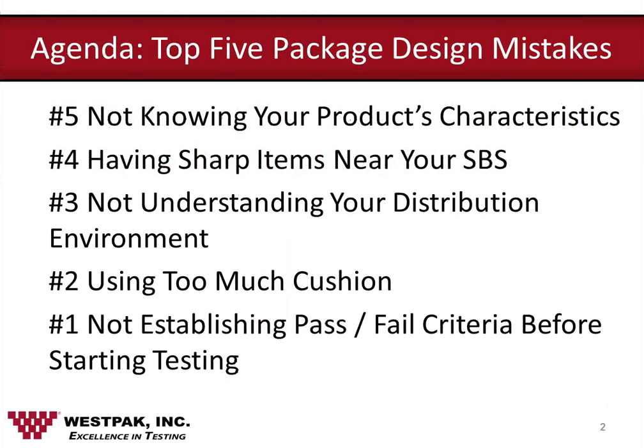Thanks, Tim. We're going to go over the top 5 mistakes people make when designing a package. This is the agenda, so these are the top 5. Not knowing your product's characteristics, having sharp items near your sterile barrier system or SBS, not understanding your distribution environment, using too much cushion, and the number 1 mistake we see people making is not establishing pass-fail criteria prior to the start of testing.